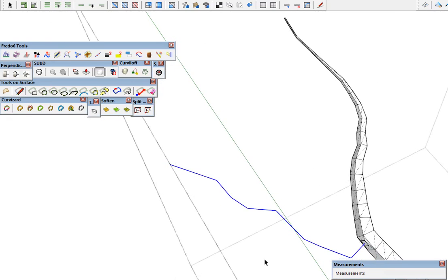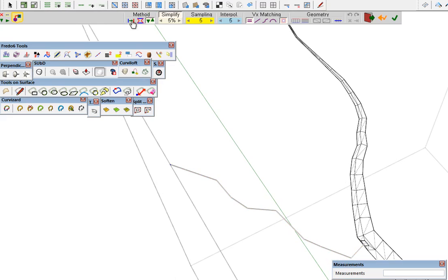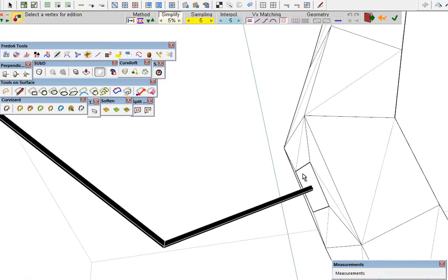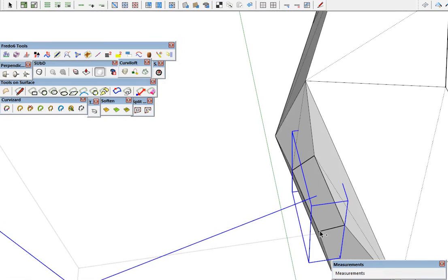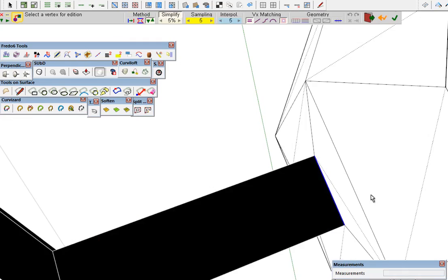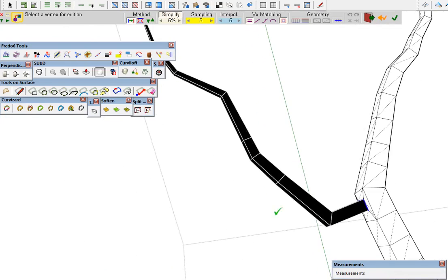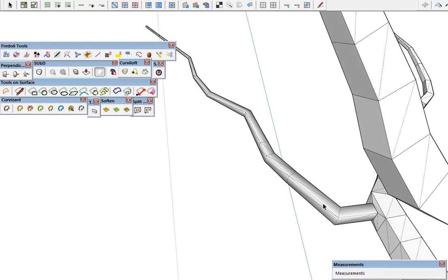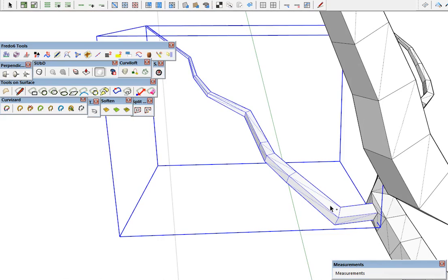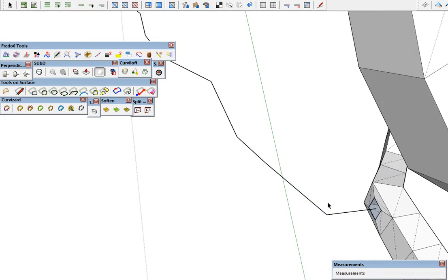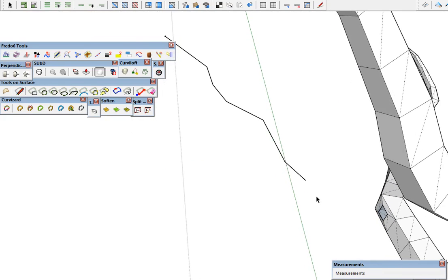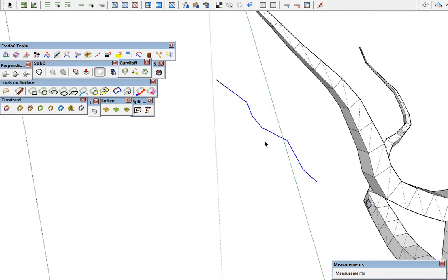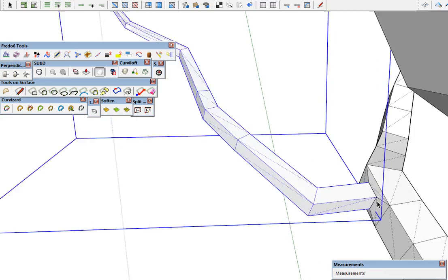But now let's grab this one and go to Curvy Loft, change our method, and we didn't have this one selected, so let's select that one. There we go. Say OK. And we'll get in there, we'll unsoften that, we'll cut it, and we'll delete these here like we've been doing. Paste that back in place.